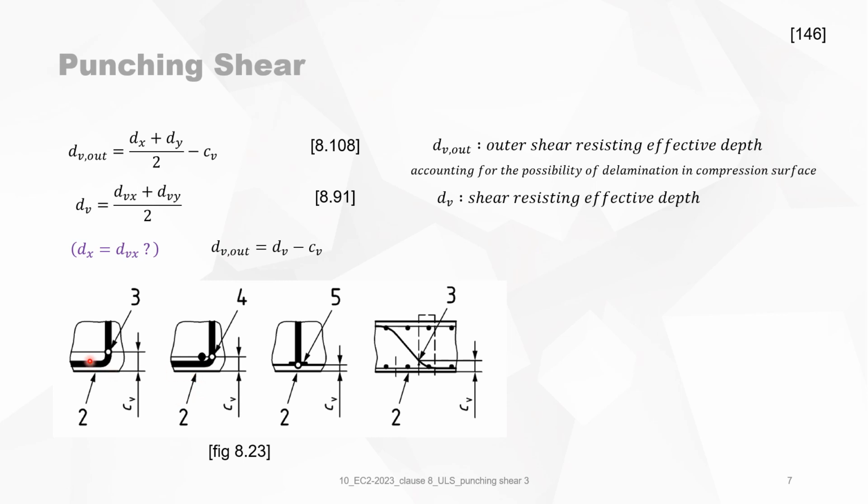In this case, when there is a rebar, which is almost always the case, and there's a rebar in the longitudinal direction, then you get here to 0.4. But what's 0.4? Is it the point of gravity of the longitudinal reinforcement, or is it at the end of the bend? This looks further away than this one, so it's not very clear. I suppose that this is the point of gravity of the longitudinal reinforcement.